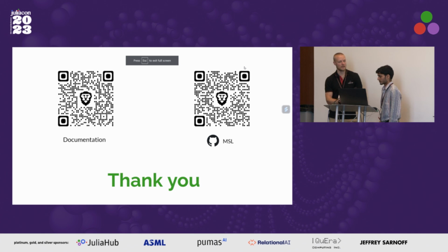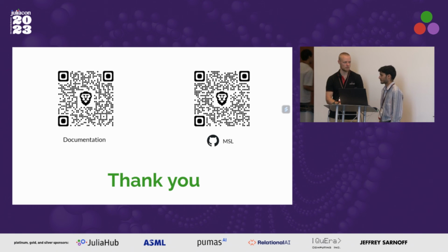So they are things like a source. Here is a sinusoidal signal that only has an output. It's things like an integrator, which integrates the input to provide an integrated output. If you are building models that take inputs, try to make use of the components called real input and real output, and eventually Boolean and integer inputs and so on, because that would make it fit together with a lot of other tools that rely on this kind of input and output functionality. So that's one thing you could potentially keep in mind.